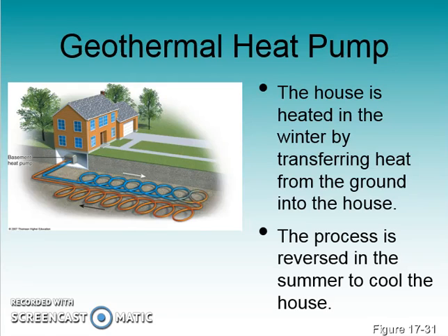Another option is a geothermal heat pump that we can actually do in houses, though not many people do it. You put a series of tubing, or netting, for water to run through, piping, in the ground. A few feet under the ground is the same temperature year-round. So it's like 60 degrees year-round. It doesn't matter where you are. It just is that temperature year-round.